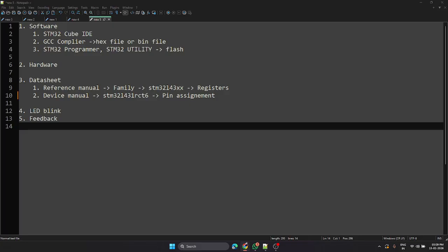Sorry. Yes. Actually, one requirement from Hindustan Unilever (HUL): they want to display the time and temperature data. They will give the temperature data as a 4 to 20 milliamp input. I need to display it on the P10 display. The 4 to 20 milliamp input option is not available in any of these ready-made Huidu controllers, so I need to use an ESP or something and send it to this display. That is the place where I am struggling now. Normally, in other places I have done it with 7 segment displays. Now I am trying with this P10 display also.